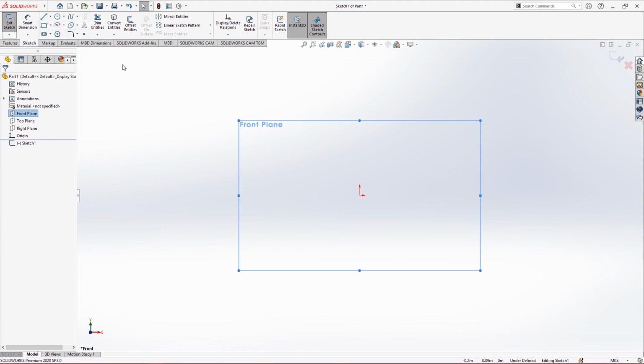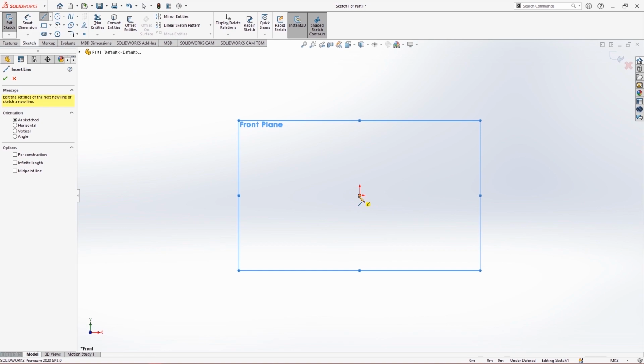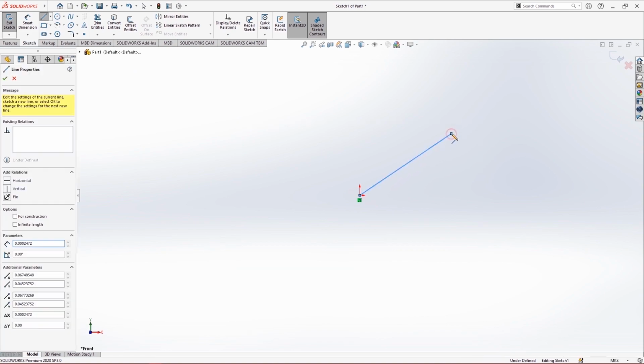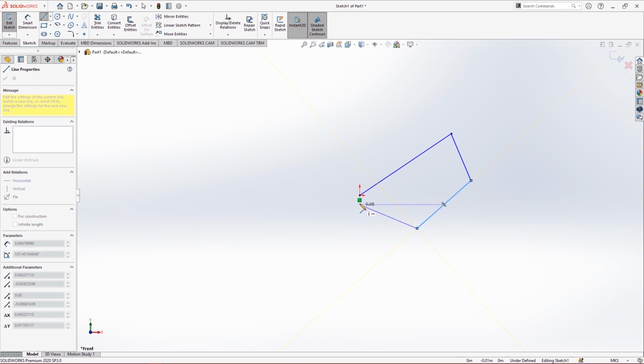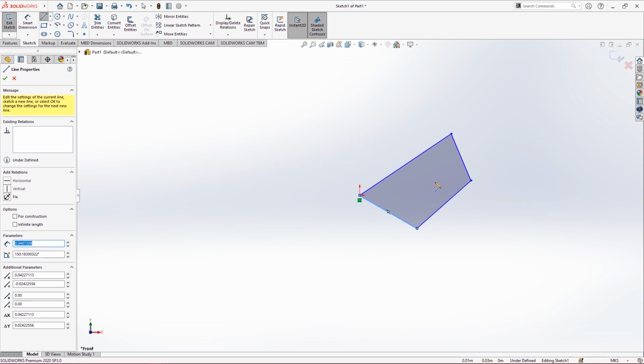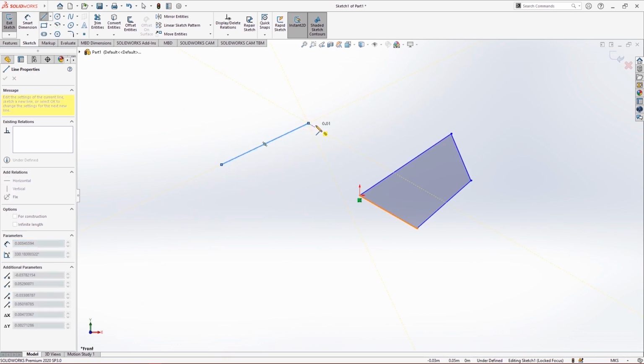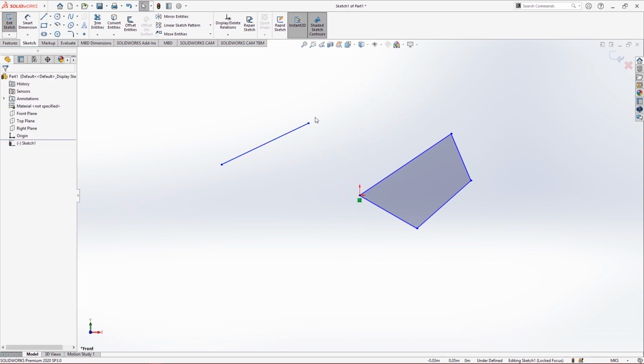The first one is a line, the simple one. Here you get 2 points of a line, the first one and the second one, then you draw a line. When you complete a line, you can still make a third point, and again it will draw a line between them, and then again a fourth one. If you click back to the first point or any of these, then it will actually close the particular geometry. For example, if I click here, the geometry will be closed. Now we have made a shape. If you just want to make a single line, you click here and you just right click and click on select, and we are out of the line selection.